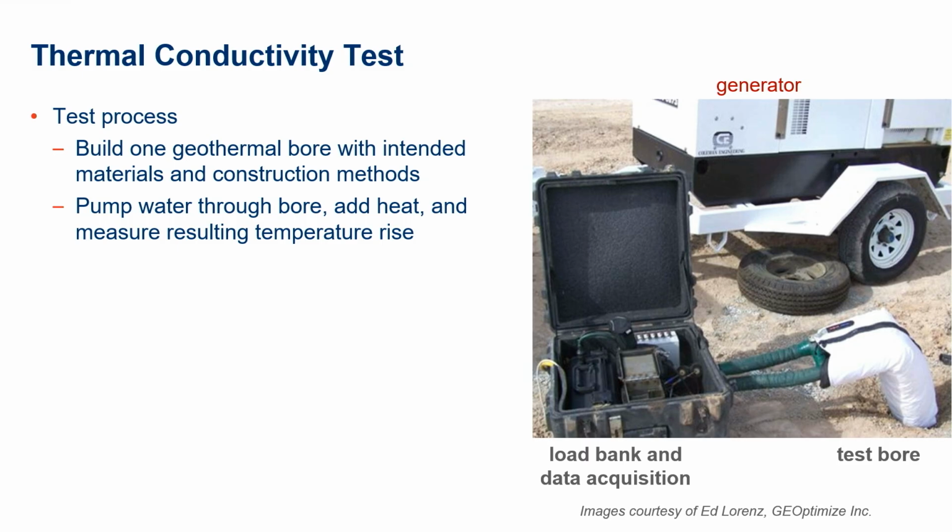Water is pumped through the bores, and a heat load bank adds a constant amount of heat to the bore for about 2 days. Temperature sensors record the water temperature into and out of the bore. The resulting temperature profile has an inverse exponential decay, and the curve fit for it yields the thermal conductivity value.